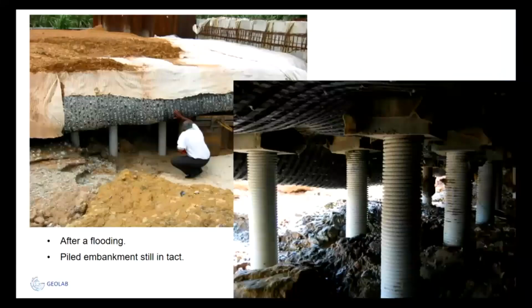For example, you can have a consolidation of a layer, like in this case, but you can also have erosion, so some water leakage or some water flow through sand, and when the sand can go anywhere, then it will go there, and that leaves a gap. Or you can have soil that dissolves, like karst stone that just dissolves in water.